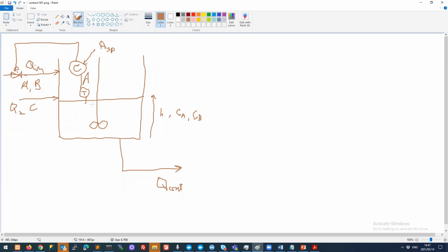There's a measurement here of A. It will compare A set point and A actual, and then it will tell the controller, I need more of the stream to enter or less of the stream until I reduce the error. When we talked about the PID controllers, you might apply a PID strategy here. That's not the only one, but you apply some strategy, and that tells this controller what action to take to try and maintain that concentration.